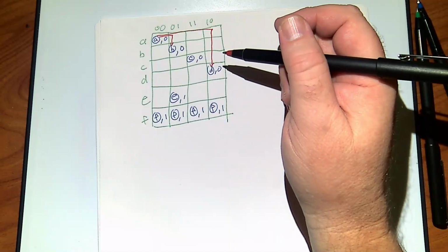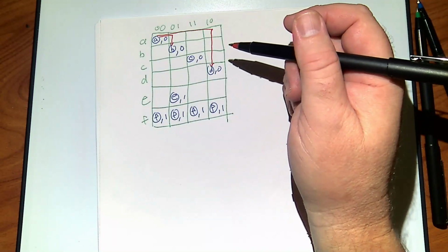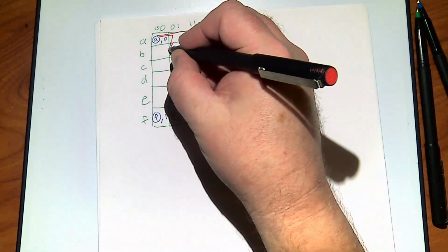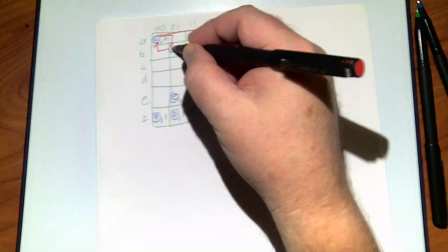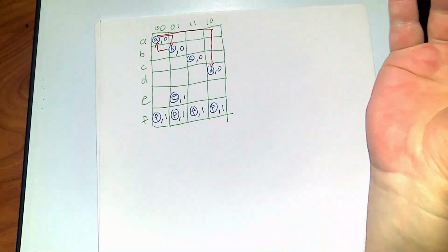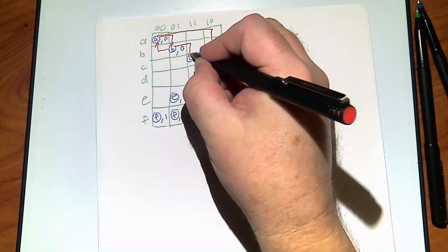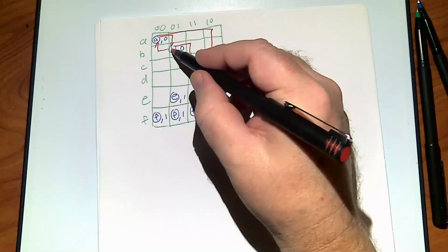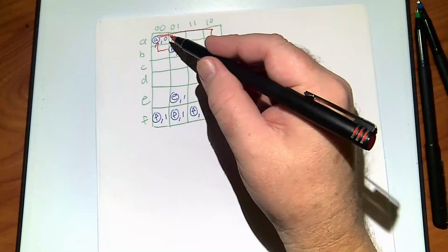Now, on these, I can take a look at each one of these in turn. So maybe I make B, and B can, right, it's in the 0, 1 column. It's nice and stable. If it goes to 0, 0, maybe it goes back to A, and on 1, 1, which is its other 1-bit flip, I go to C. So notice again the input changes, and then I respond to it quickly.